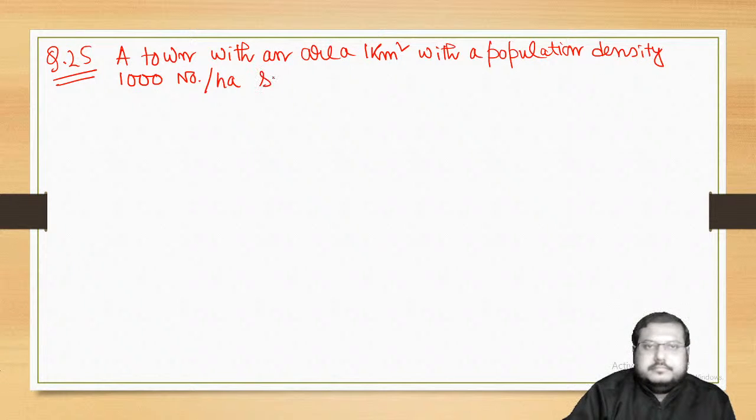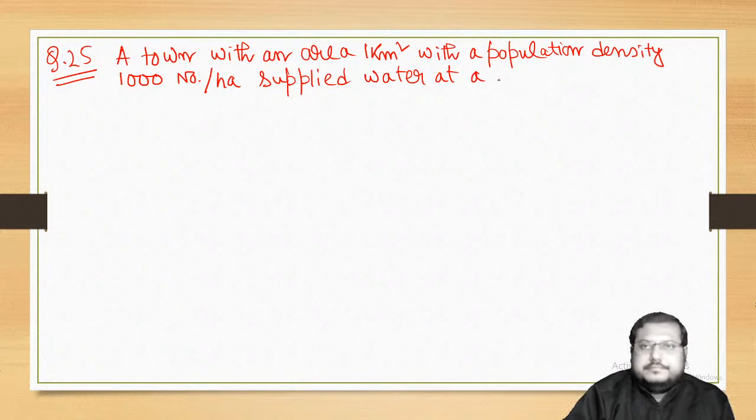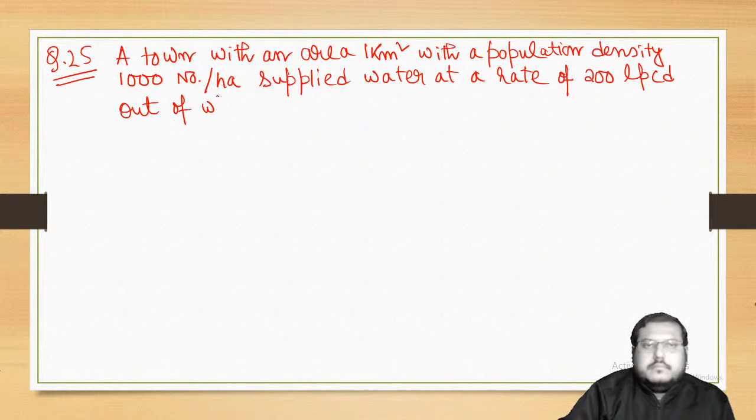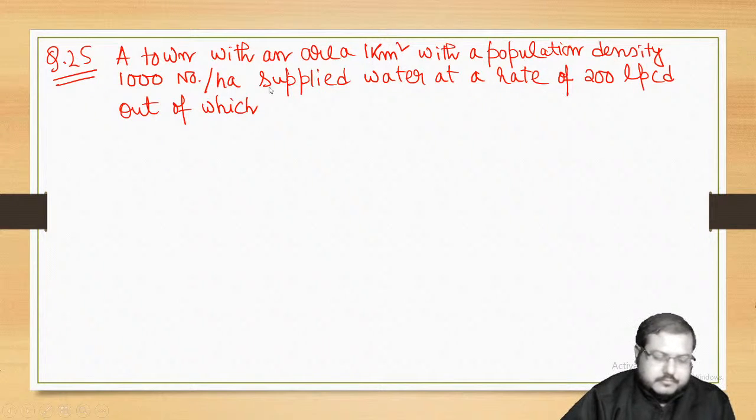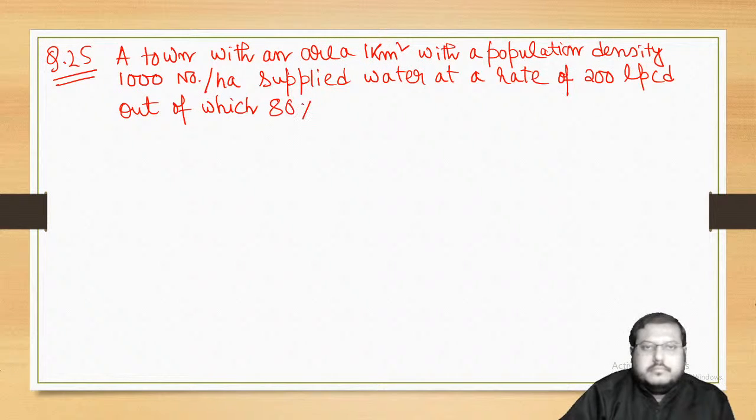Supplied water at a rate of 200 LPCD, out of which 80% reach sewer as a sewage.